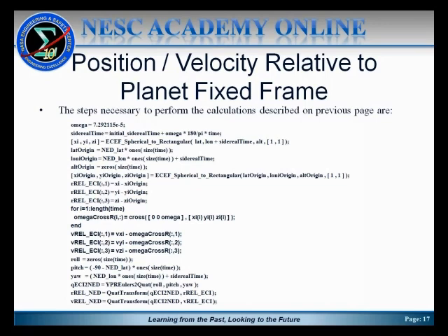Another couple of functions down towards the bottom are related to quaternion manipulations. One is a yaw pitch roll Euler's to quat, which computes a quaternion for 3 given Euler angles in a yaw pitch roll sequence. There's also a quaternion transform function at the bottom, and most of the time you could find either in toolboxes available from MATLAB or Octave or whatever application package.